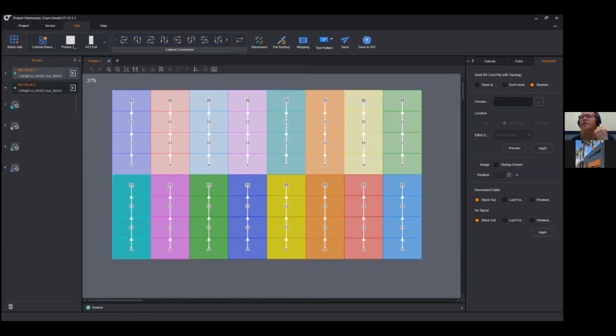Let me start with the pros and cons of configuring redundancy versus using separate senders. Yes, there are a lot of pros. This way works. You don't have to use the reverse path. That really isn't the correct way. If you wanted to do non-cascaded senders, so that's two senders that aren't talking to each other, you would load the same screen configuration in both of them, not a reverse configuration, and then you would tell the primary sender, hey, you're the primary, and the backup sender, you're the backup.